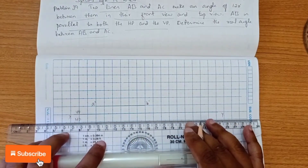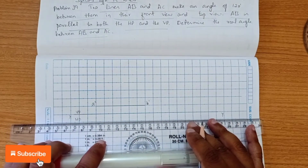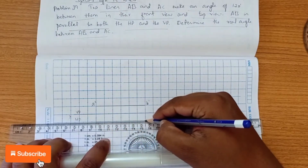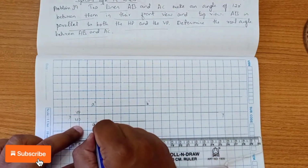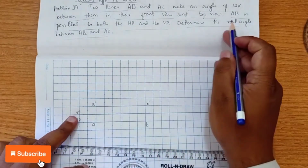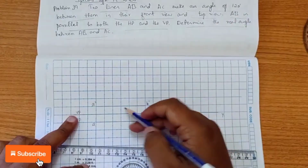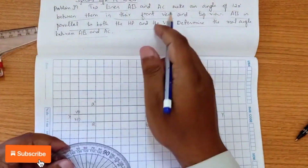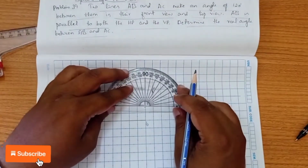In the same manner here, parallel to it, because the AB line is parallel, I am considering 60 mm. So this is B. You can see that line AB is parallel to both HP and VP. Now AB and AC make an angle of 120 degrees.